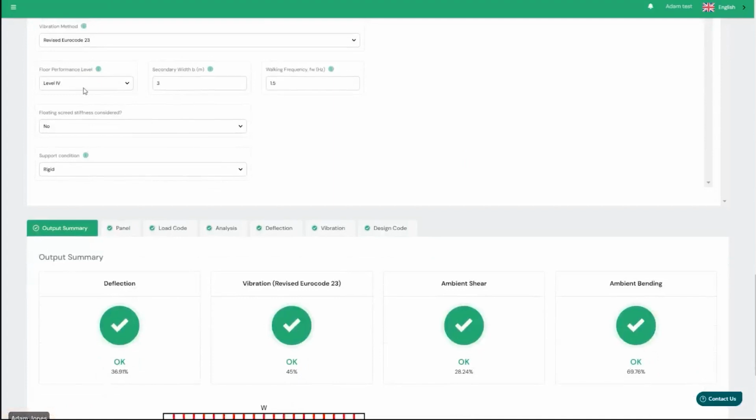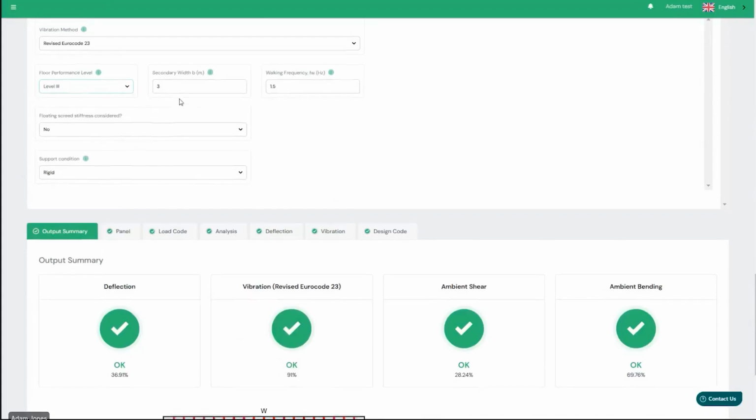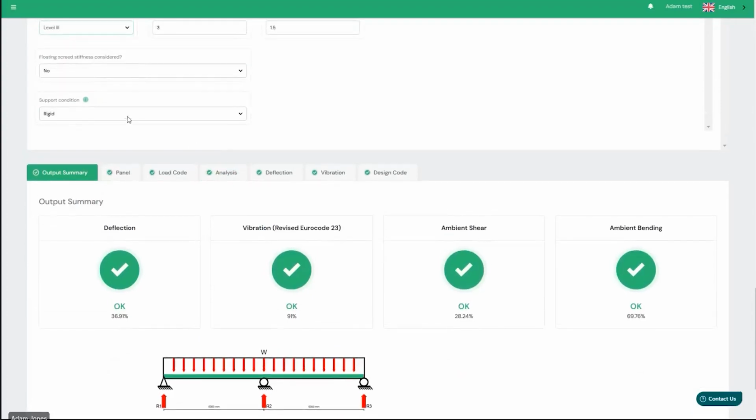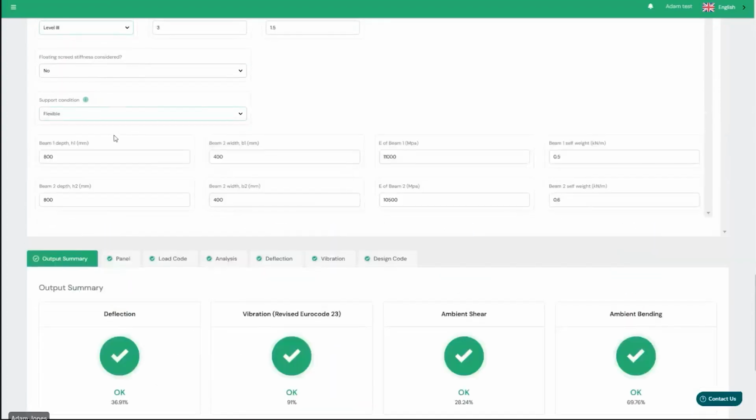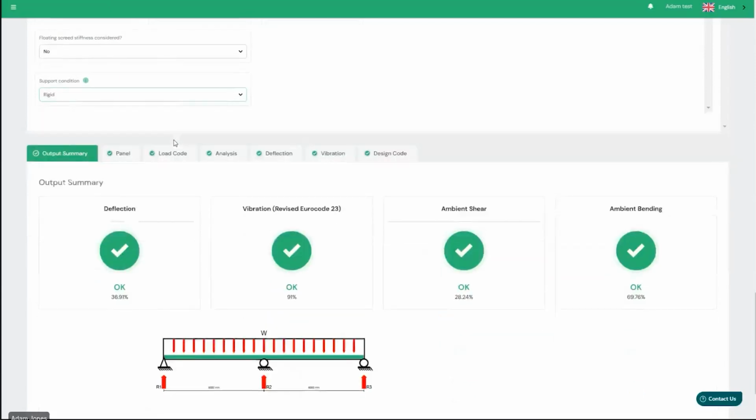And you can see here, as we go to level 1, it doesn't work, but you can go through your client and negotiate with them what's the actual level we're choosing to. And as you fine tune that, you can actually get the costs right from a mass timber supplier point of view. It's also got now flexible supports or rigid, and that means you got supporting beams contributing to it, so it's working as a system. So you can input in your beams, and as we design our beams, you can come back in and update the stiffness there, assuming we were to be flexible or rigid.